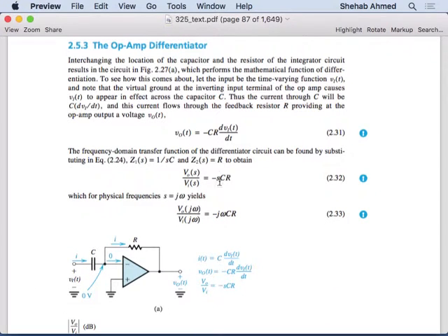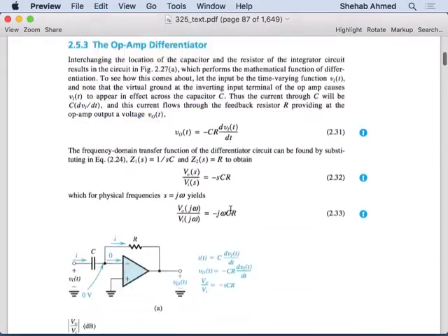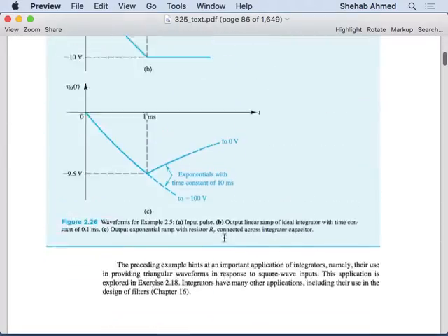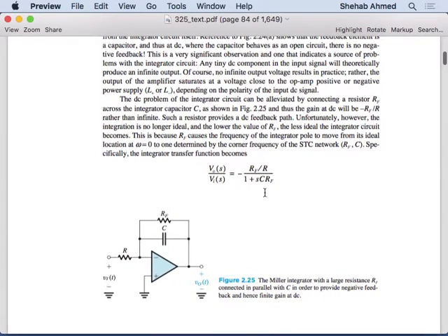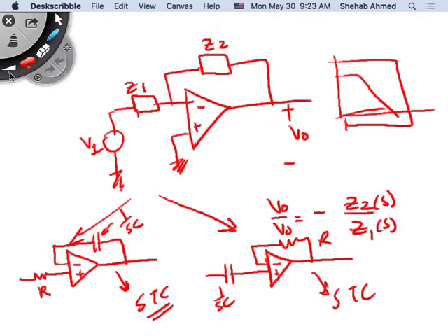Meaning, if you look at here, this was the general case with the integrator, for example, with an R, was a single time constant transfer function, right? So we had DC gain, we had cutoff or break frequency. You had reduced it to whether it's a low pass or a high pass. The differentiator was a high pass. The integrator was a low pass filter. So assuming we're talking about the integrator, we're talking about the low pass filter.